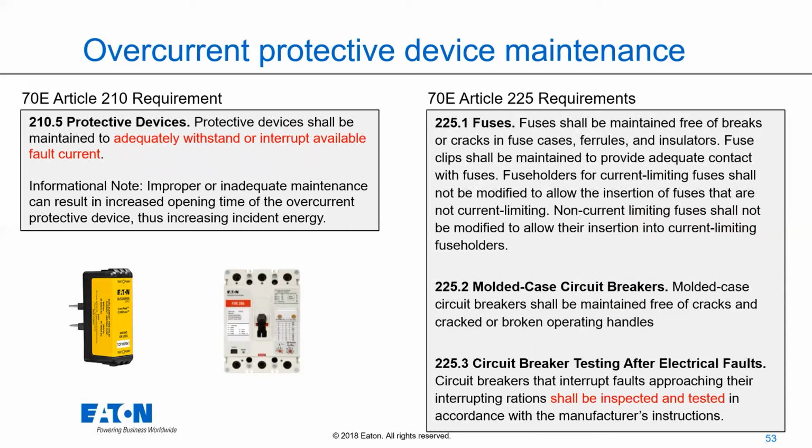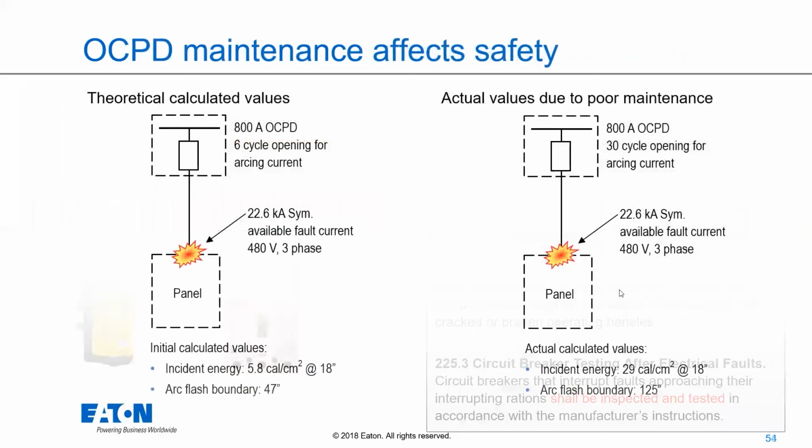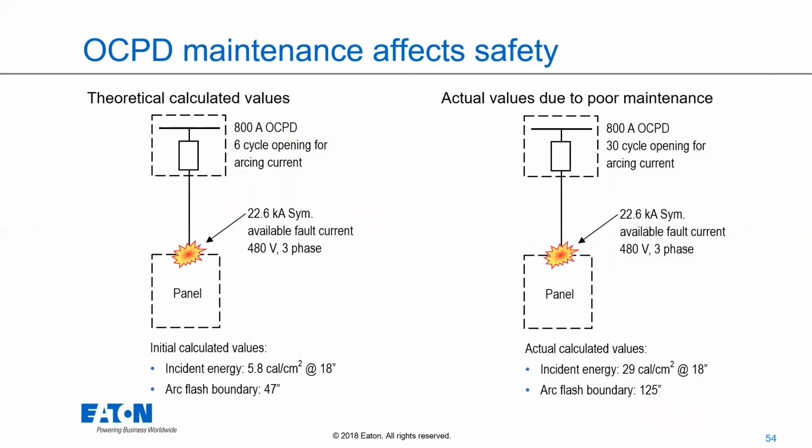People have told me one of the most obvious things is actually the way that it smells. A breaker that has interrupted too much fault current has a sort of burnt-ish smell to it. So if you have a smelly breaker, you probably want to replace it, in addition to obviously looking for those cracks.